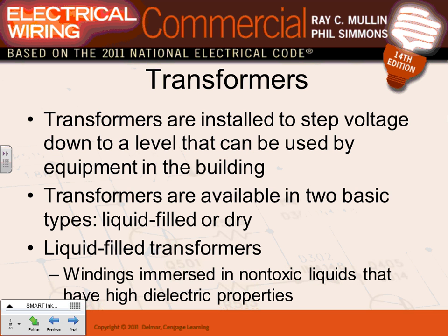Transformers are available in a couple of types, basically either liquid filled or dry. Typically, most of what you guys are dealing with in a building are dry type transformers, but you can have liquid filled. Liquid filled have the windings immersed in non-toxic liquid. Anybody want to guess which one is the better transformer, in terms of being abused and used and giving more power? The liquid or the dry? Liquid. But which one is dangerous? Liquid is dangerous. That's why we don't use them a lot in a commercial or industrial building.